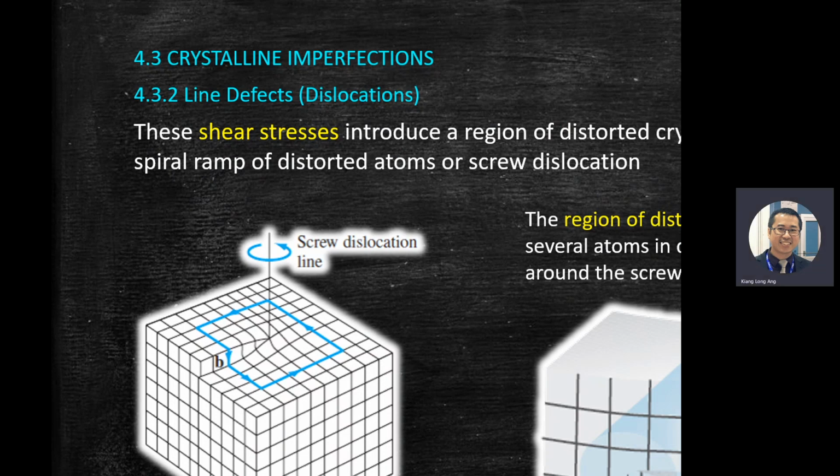So it's pressure, or in materials or engineering we call it loading, or force, depending on what you define. The force is perpendicular to the area. To calculate the stress, force divided by area, but it must be 90 degrees. If we have two forces pointing out, it becomes tensile loading or tensile stress.